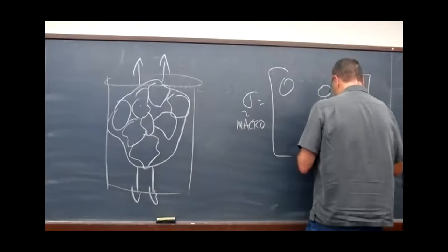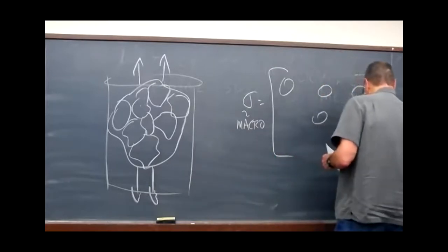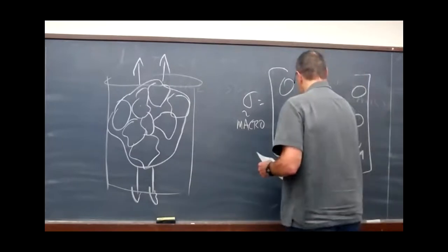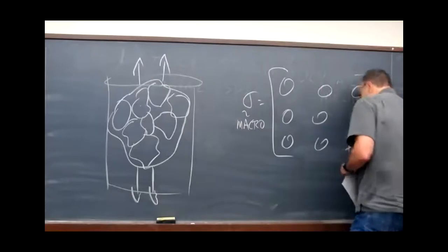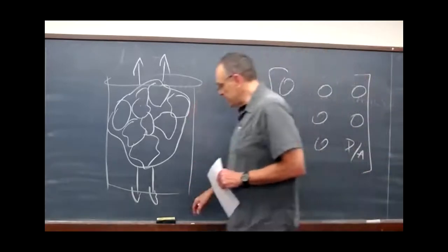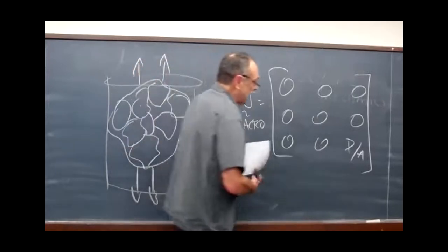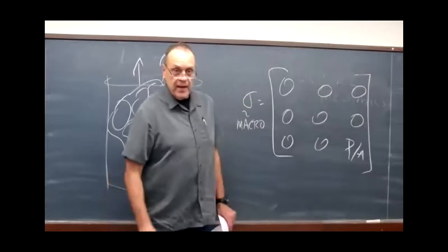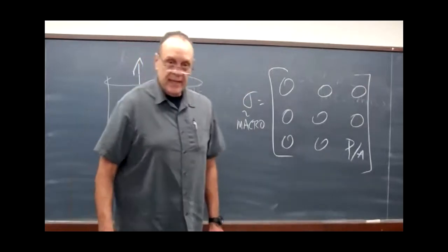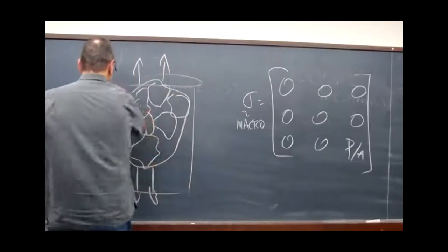And we just put it in matrix form, and we have our set of basis vectors. For this uniaxial experiment, just by the nature of the way that it is set up, the only non-zero value of stress in the stress tensor is just the load over the area in the E3 direction.